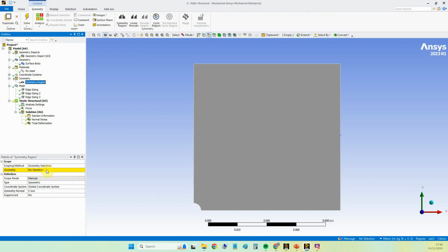So it's looking for geometry selection. Let's select this one. This is going to be the one that's at the X direction normal. So let's go OK to that. And again, like I said in the previous truss example here, we're going to define the normal to this symmetry plane. So this symmetry plane is the YZ plane, and it's the X normal. What's the direction we want it reflected in? In this case, that's already set to X. We don't have to do anything.